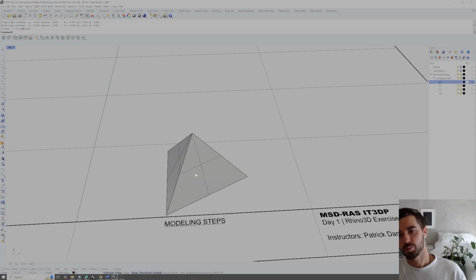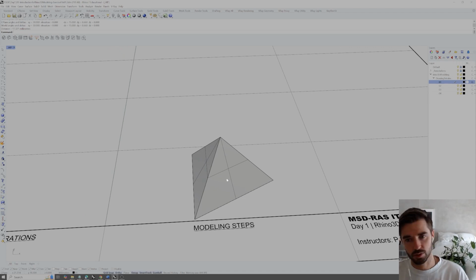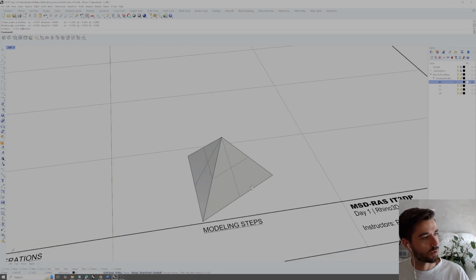So by modeling the pyramid this way, since we're defining 2 different aspects, one is the height and one is the radius of the circle in which the pyramid base is inscribed, we're not actually resulting in even equidistant edges. So you can see here we have 14.142 and 17.321.